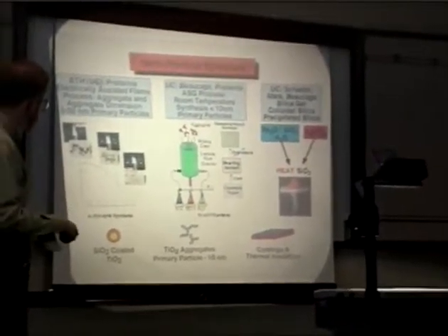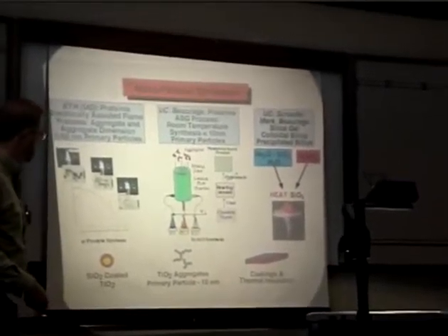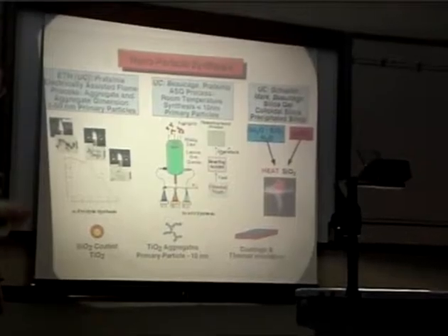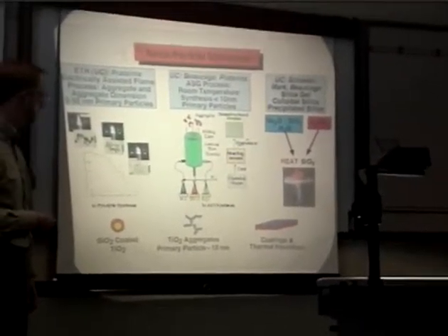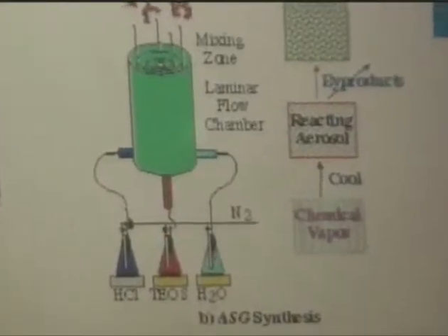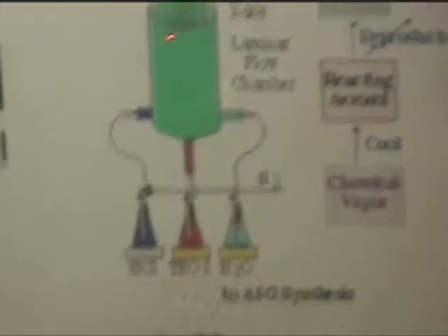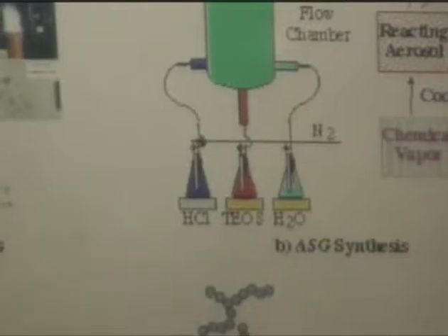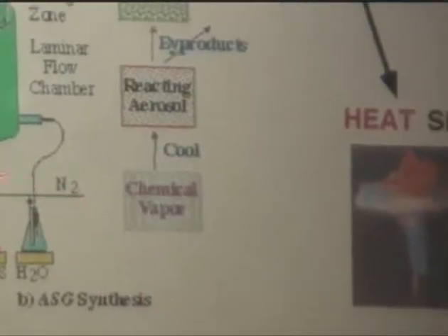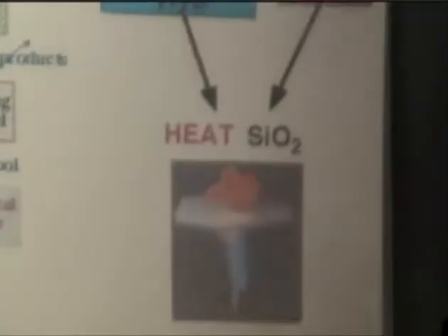We make a vapor like in the pyrolytic ceramics, but the vapor is made of chemical reactants. We never heat it up. It's all done at room temperature basically, except you need a certain temperature to keep the reactants in the vapor phase. We mix the reactants, they condense into a cloud, basically like a cloud you see in the sky, and they rapidly form ceramic oxides.